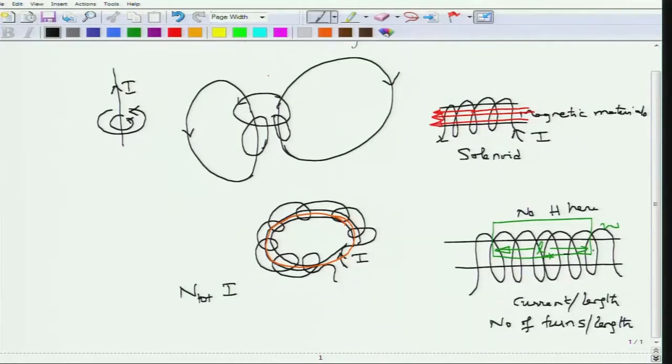Okay. And what would be the left hand side of Ampere's law? If you have forgotten Ampere's law, this is Ampere's law: the integral of H dot dl is equal to the total current enclosed. So we have actually obtained the right hand side, the total current enclosed. For the left hand side, you can observe that there is no magnetic field along the path for W, because the field is all perpendicular and along the axis.